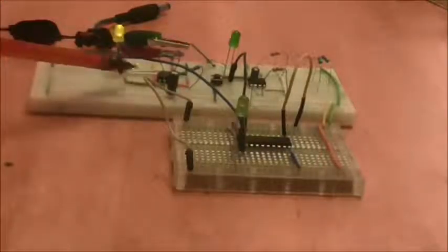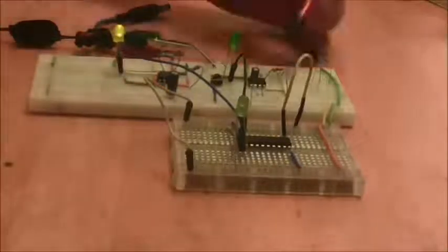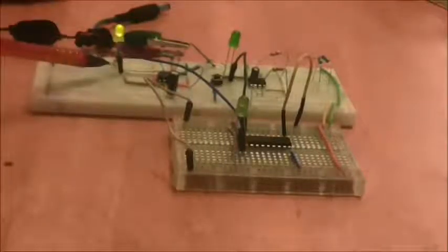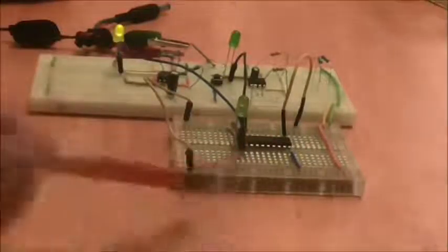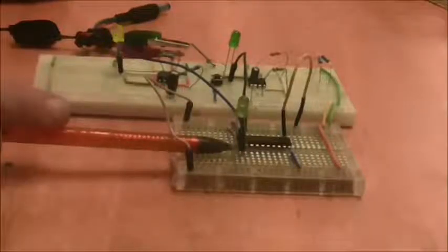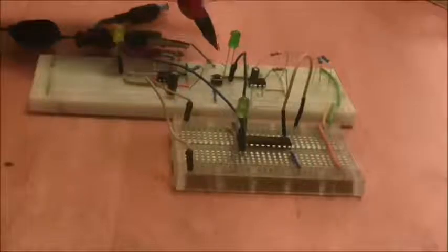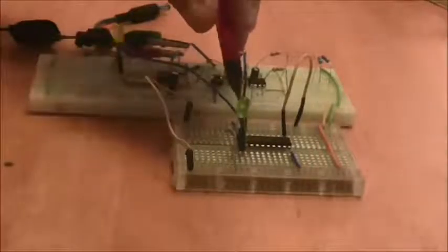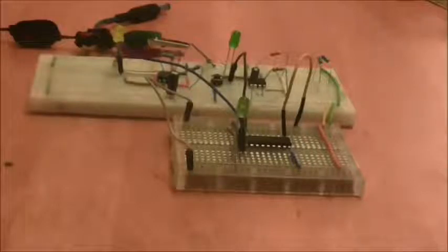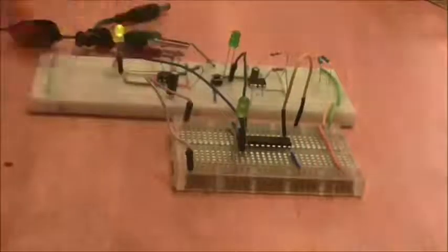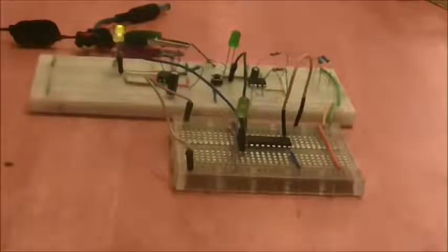This is the astable from our last experiment, and this is the monostable from our last experiment. What I've done here is I've put the output from the astable to the clock just there of the D-type flip-flop, and I put the output from the monostable to one of the inputs of the D-type flip-flop. There's actually 8 D-type flip-flops on here, and they go straight across like that, so that's input 1, that's output 1, input 2, and so on and so forth. Doesn't matter which one you use, they're all working exactly the same way.